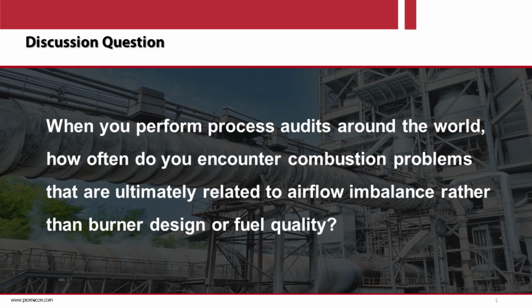In addition to that, if you have an inefficient combustion, you will face some CO spikes, and people typically try to overcome those spikes by adding more air. So your exhaust gas flow rate, or specific exhaust gas flow rate, will increase, which is easy to understand, will increase your ID fan power and the electrical energy consumption. But it also comes along with higher fuel consumption.